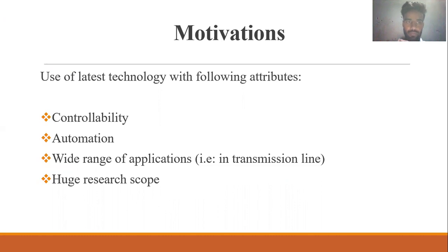First of all was the controllability. Controllability was the major factor. By controlling the thyristor angle, it was possible for us to control its mode, whether capacitive or inductive, and whether to insert or bypass the TCSC. The second one was automation. It was completely automated, which I'll explain further. It also has a wide range of applications in the coming days.